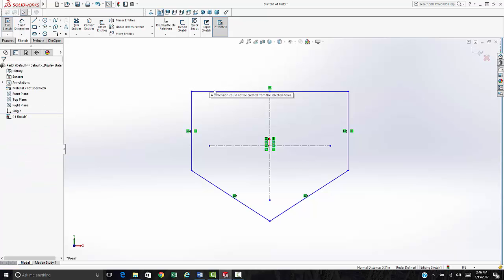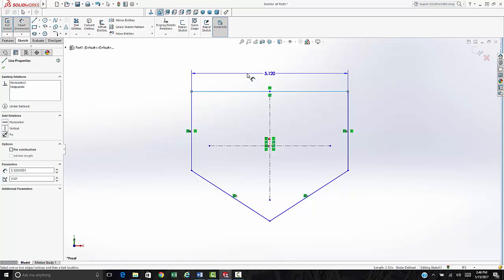So now we'll bring in our dimensions, and here is where setting up English and metric could be an issue. Because these parts here, what are these? Are these given in inches? I think these are inches, and they sure have very tight tolerance on there at 4 decimal places. Okay, I'm going to interpret those as being in inches.